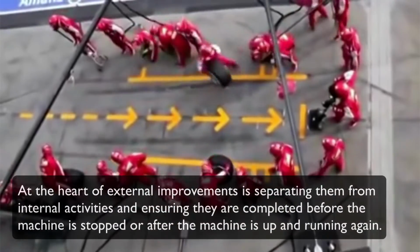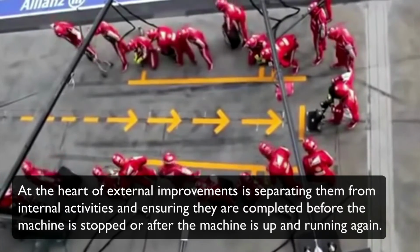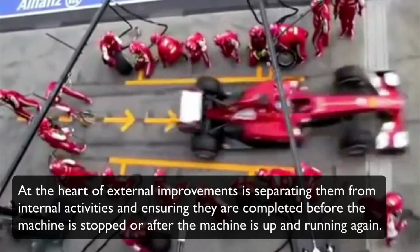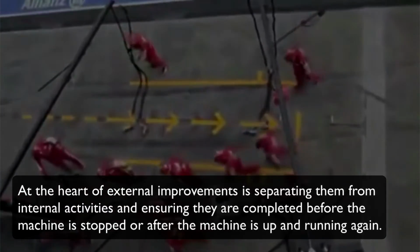External or internal. As you've learned, external activities can be performed while the machine is still running. At the heart of external improvements is separating them from internal activities and ensuring they are completed before the machine is stopped or after the machine is up and running again. So, what can we do to improve activities that must be performed only when the machine is stopped?